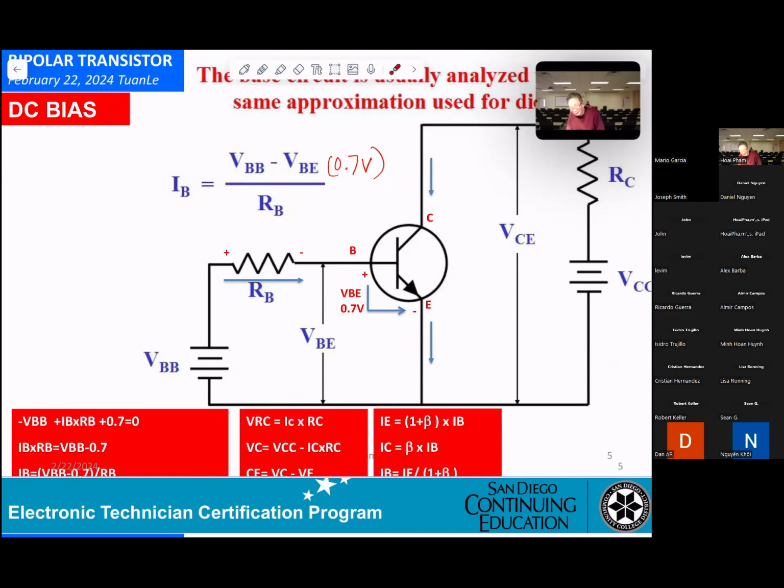However, if you want to know the value, you can run the MultiSim server. Okay, they can give you any value you want. The thing right now, we want you to try to understand: first, you're looking at the transistor, whether it's NPN or PNP. Second, if it's NPN, then the voltage from the base to the emitter is 0.7 for a silicon diode.